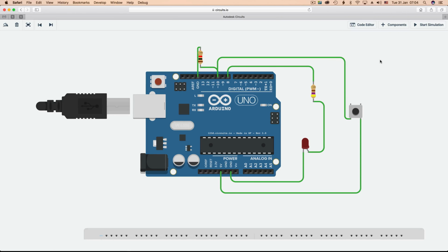I will explain to you how to wire up your circuit. Get a push button, and if you have a multimeter, measure which pins get connected when you press the button. Wire up one of the sides to 5 volts, and then the other side to pin 10. Make sure that you have a pull down resistor of a value of about 10k to ground from that pin.